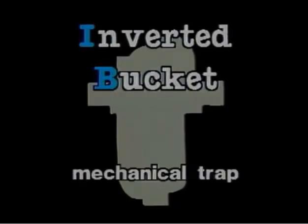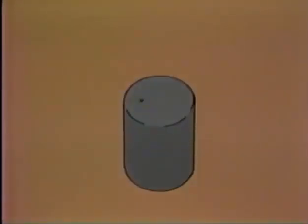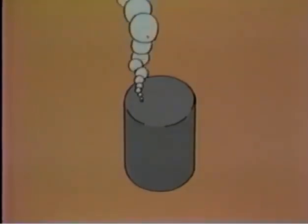The IB steam trap is a continuous drainage, intermittent discharge device that operates on the mechanical principle. The heart of the inverted bucket trap is this bucket. In the inverted position, it acts as an open float. It is capable of functioning under very high pressures because the same operating pressure is exerted both inside and outside the bucket. A small orifice called a bucket vent is located at the top of the bucket to ensure that non-condensable gases cannot be trapped inside the bucket.